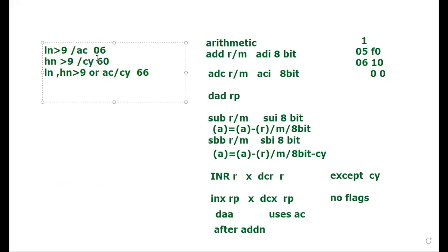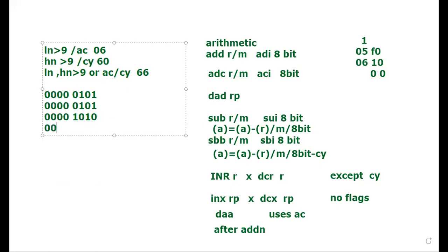For example, say 05 plus 05. Your answer is 00001010. The lower nibble is greater than 9, so the microprocessor will add 06 in the answer. So you get the answer as 00010000. That is, the answer will be 10. So 5 plus 5, the answer it made 10. So all the three conditions you will have to show.